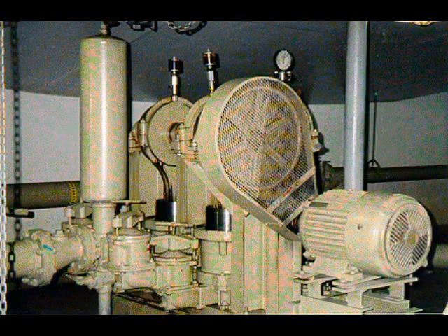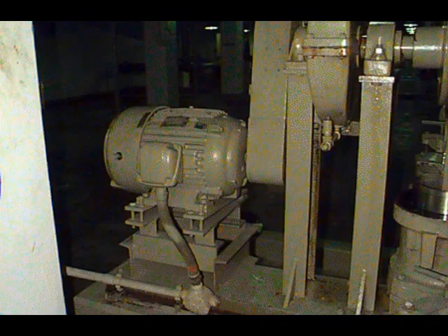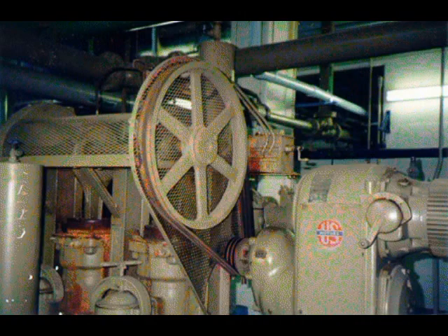Now let's see how the plunger is driven. This photo shows a typical plunger pump motor and the first V-belt pulley arrangement. The motor speed is reduced to about 50 RPM, or 50 plunger strokes per minute. The first pulley system provides about half of the motor speed reduction. This pulley system transmits its torque to another pulley system.